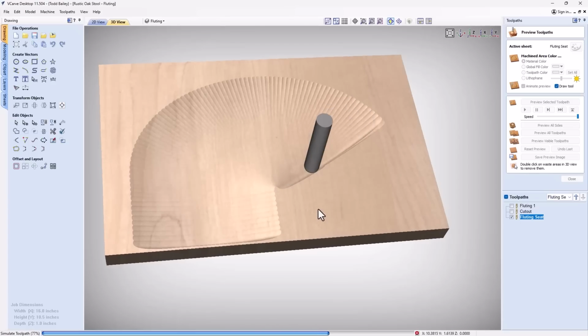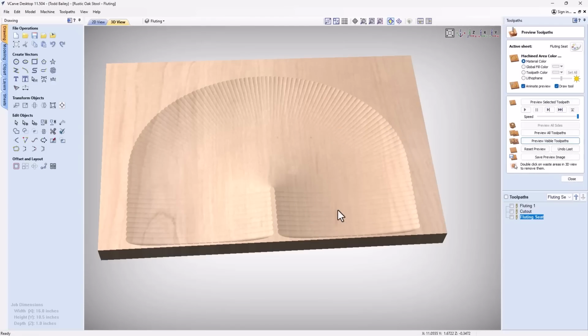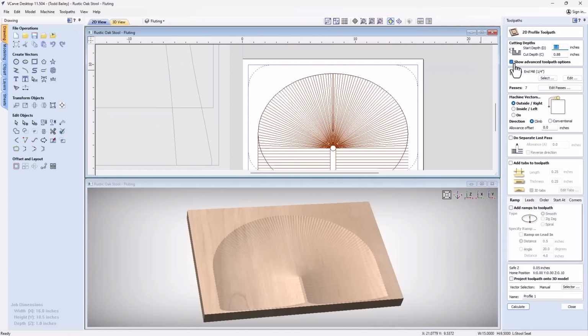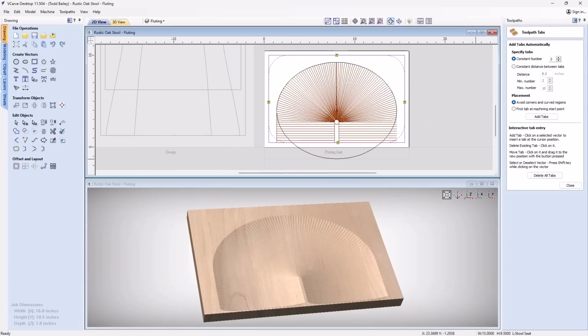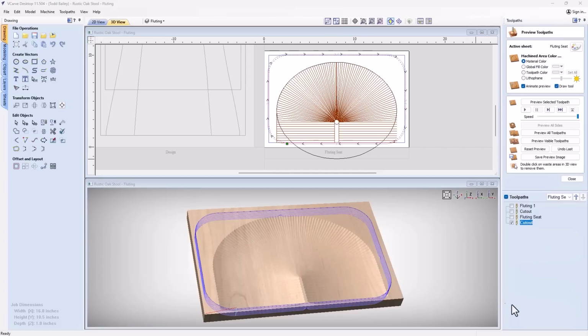Now once this is all done and I'm happy with it, I'm going to create the cutout pass for this, and then we'll move on to actually cutting it on the machine. You'll notice that I've chosen to use 3D tabs for this job, and they're a bit small. Don't panic. In the file that you're going to get, these will be larger. In the actual cut file that I cut, they were quite a bit larger than these little ones, so it was super safe.